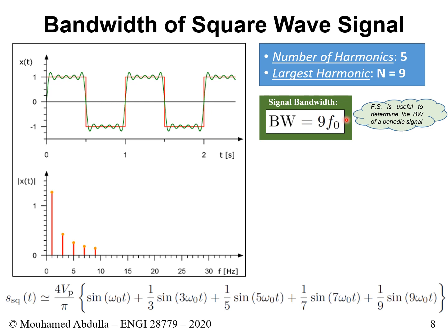So we want to do that. Sometimes we could say also increasing the bandwidth increases the speed. In that sense, yes, we want that. But from a resource point of view, you want to have less bandwidth. We want to use less bandwidth to convey more information. And there are many reasons why we want to do that, but one key reason is in order to enable multiple users to use the same channel.